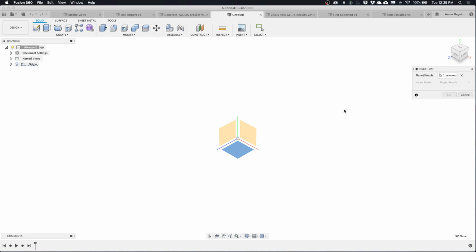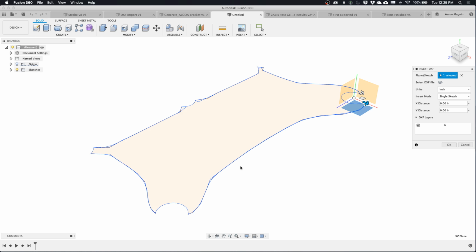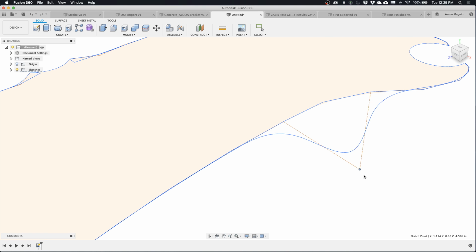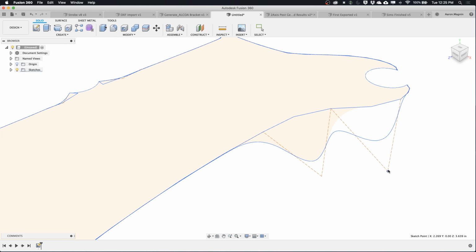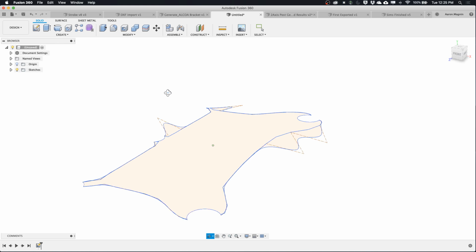So when you go out to DXF, you might lose a little bit of that spline information, or you might lose the ability to edit it. But now with the most recent changes to Fusion 360, it's actually going to reconvert those into editable CV splines. So this works with AutoCAD files, and this works with DXFs as I'm illustrating here. So you can see there's control points in there to select and move around and take advantage of.